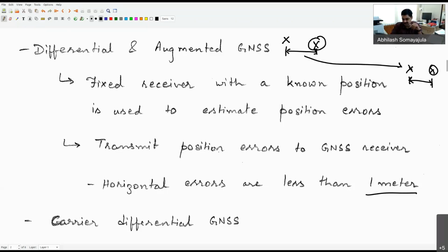Remember that GNSS is basically sending an electromagnetic wave from your satellite to your GNSS receiver, and you're basing it on the time difference between when the satellite signal was stamped and sent and when it was received, to find out the triangulation of it.